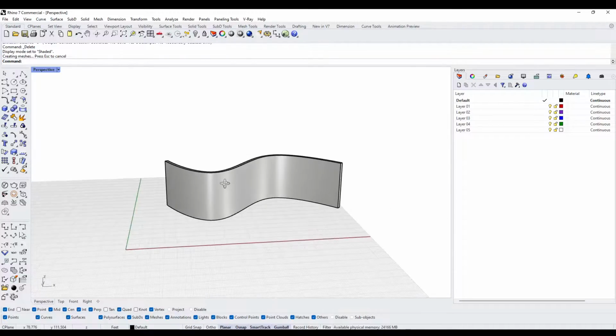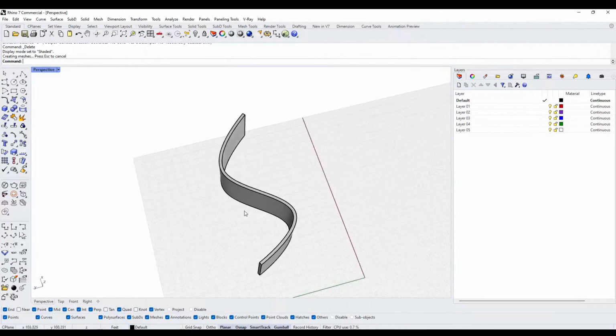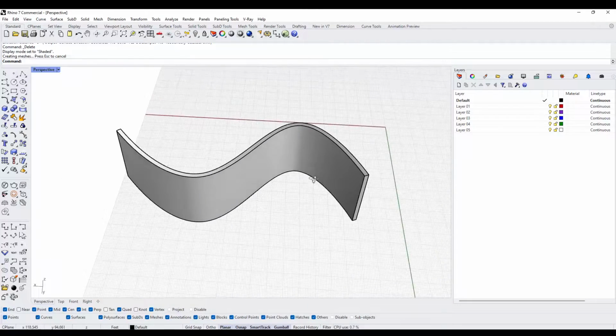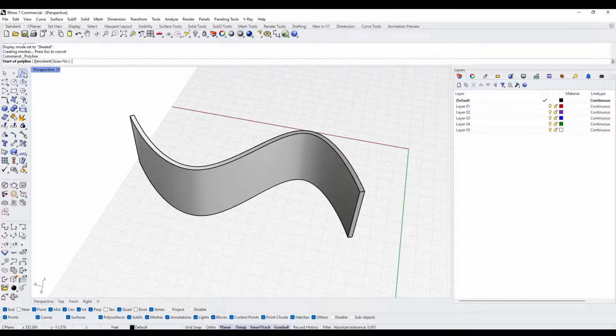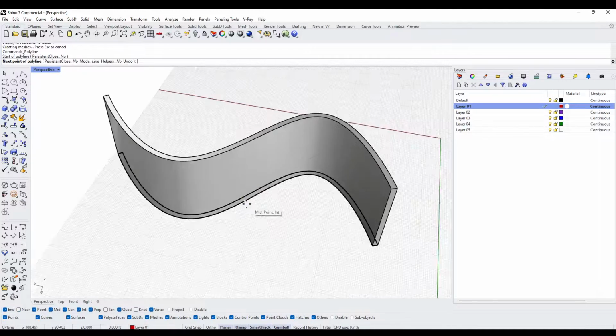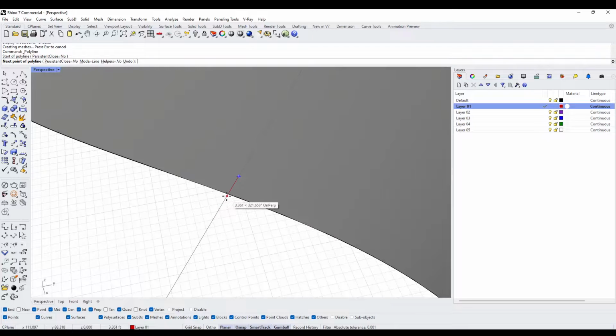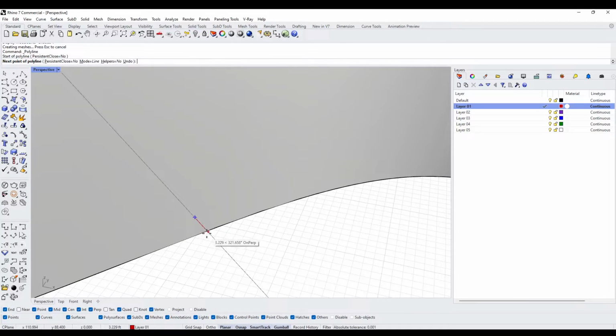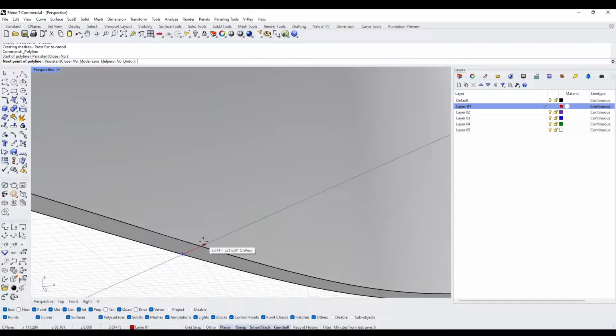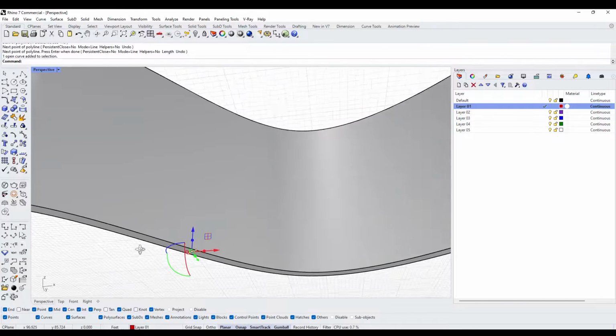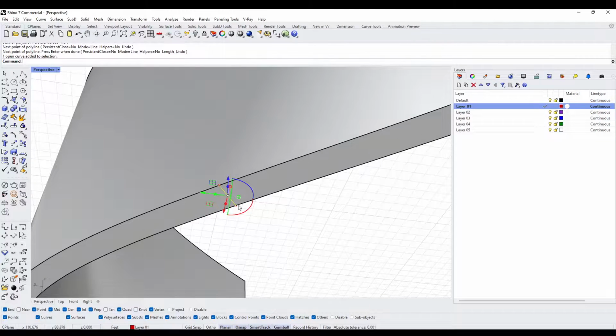And with a wall like this, what you would need to do is pick a point along the wall where you want the opening. So let's say we'll go here to a polyline, then we'll go to nearest, and then I'll just pick a point along here. If you want it exactly in the middle, take off near, and then we'll go here to the middle, to this other side. And I will use the perpendicular snap.